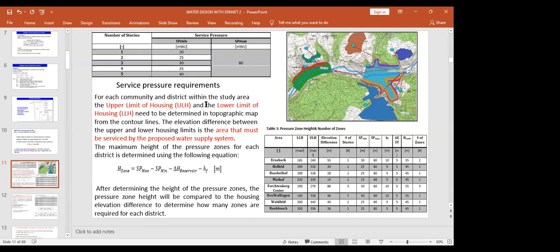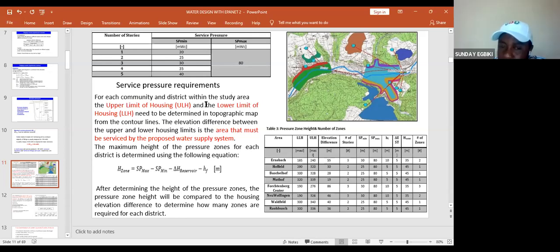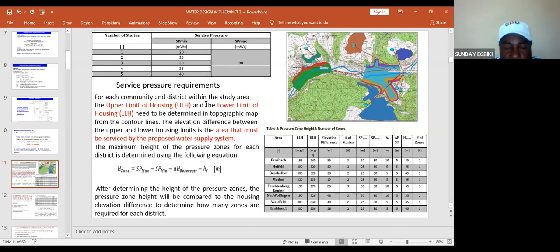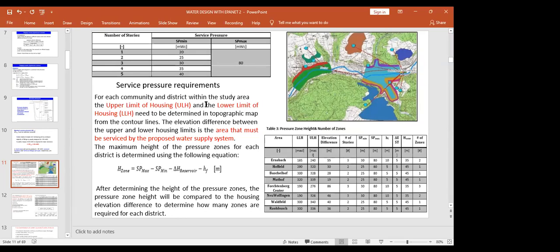Is the 10-meter a rule of thumb estimate? Yes, for a municipal water distribution, at the consumer tap it is 1 bar. There must be a basis for that. I'm trying to understand. It's like a design code. When you have a design code where you pick values, there's no need for you to derive it. People have derived it and come up with it. It's an assumption in design. They are standards you assume. So we assume that in the network, 1 bar is reserved for bends, taps, and losses.